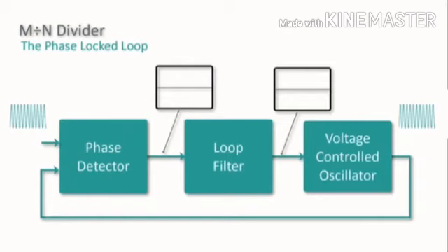That 0 output is passed to the VCO input, so the VCO doesn't change its output frequency. The loop is stable, and in this condition the loop is said to be locked. You'll see why in just a moment.